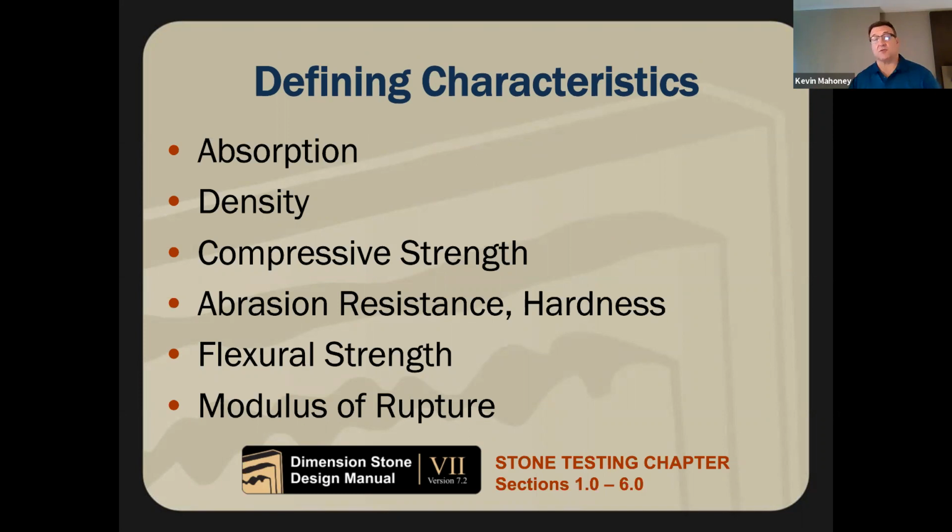The compressive strength, and slate, while it seems like a sedimentary stone, is really a metamorphic stone. So for example, the compressive strength of slate, if you were going to run trucks across it outside, may or may not be the best application for that stone. It's the ability to withstand pressure from the top. So that's important to understand, and understanding what the applications are. How much weight, what's that going to take?